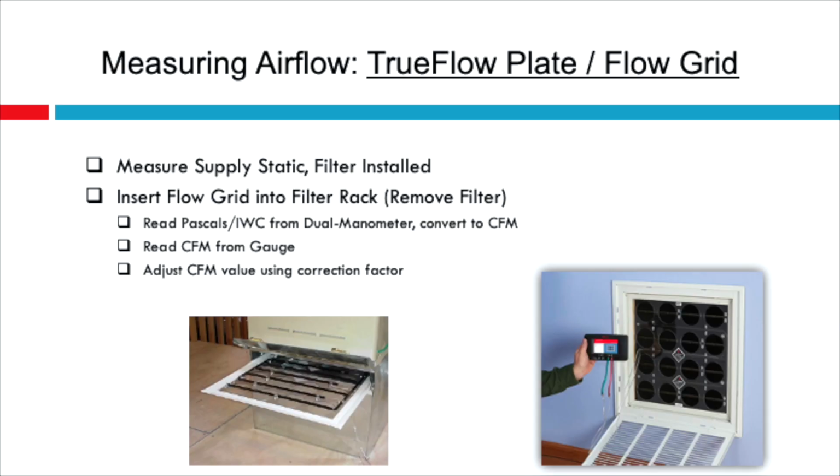Unfortunately, if you're measuring this at a filter grill, it may not include all of the duct leakage back to the system. And if you have more than one filter grill, because you have multiple returns, not a good idea to measure this at that grill. You should measure it at the unit, which unfortunately for some of you technicians means getting up into the attic.